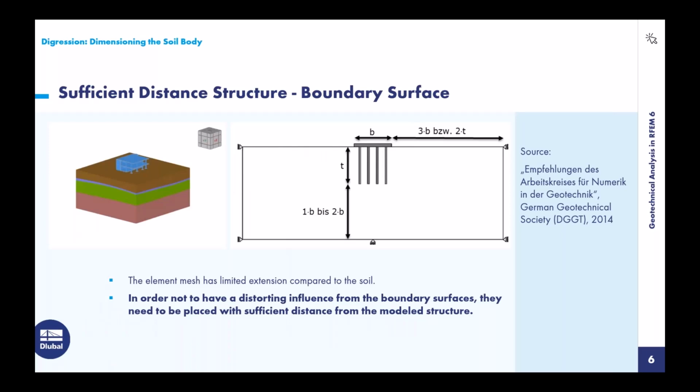This slide shall show that it's important that the supports, our soil being supported by surface supports, have enough distance to the area you are interested in, so that the support stiffness doesn't influence your result. And you can find proposals in the literature regarding these distances.